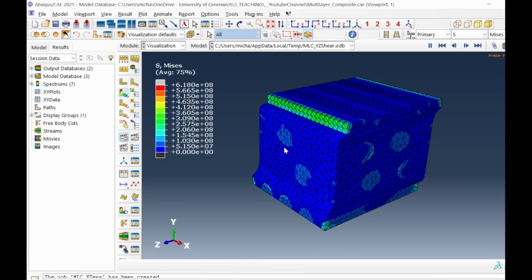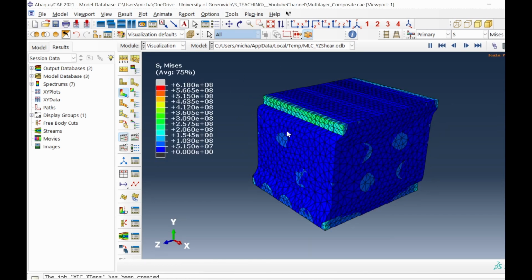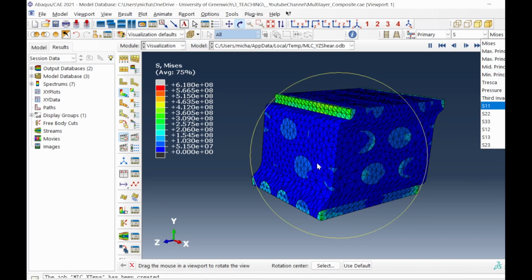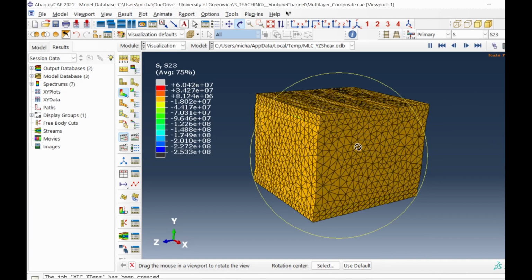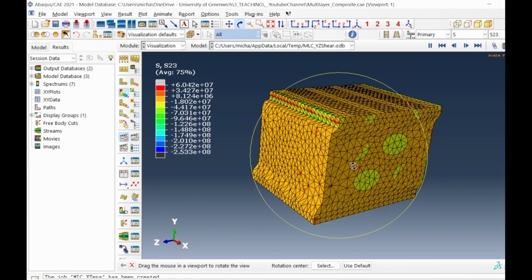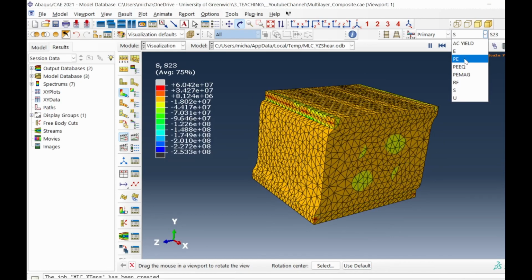So with the shear mode, we see a similar kind of deformation with the body deforming in that kind of axis in shear in von Mises style. So if we switch to, so this is shear deformation in the YZ plane, the 2-3 stress, which is what we simulated, and then we get that result. So let's look a little bit more closely at the plasticity.